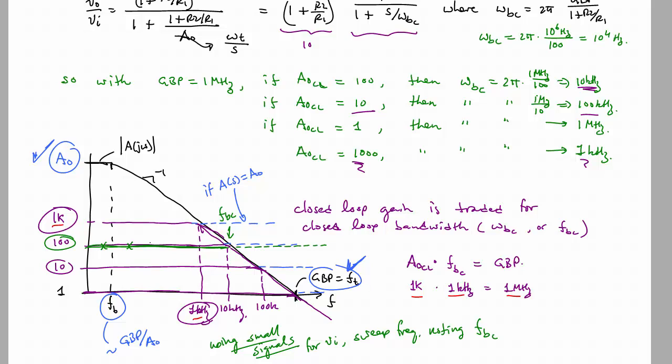So keep taking data points, and the break frequency will be at minus 3 dB relative to 100, if that's what you designed, a gain of 100. So 40 dB, you're going to be down 3 dB, in other words at 37 dB. So you'll keep moving the frequency of excitation up until you notice a 3 dB roll-off.